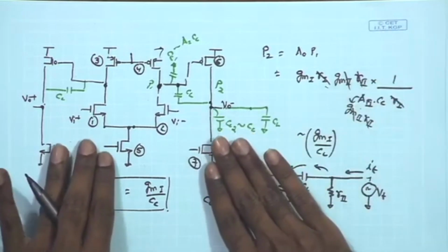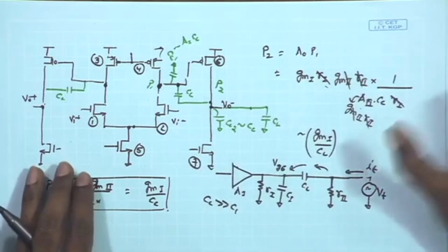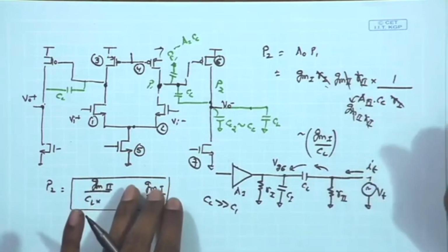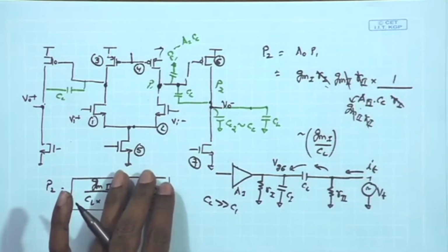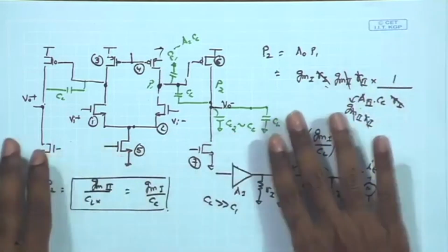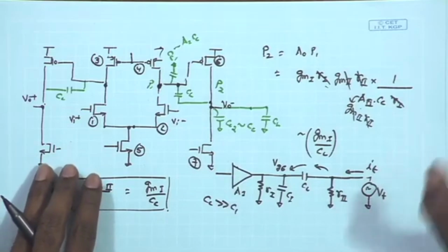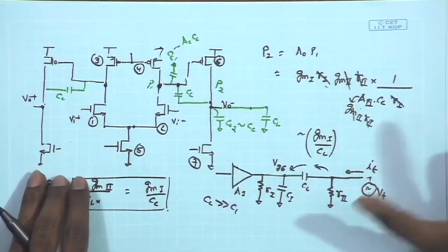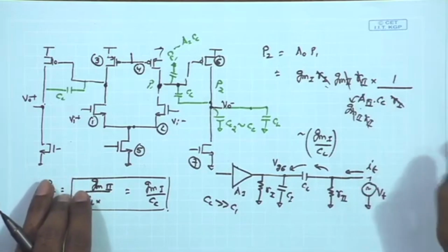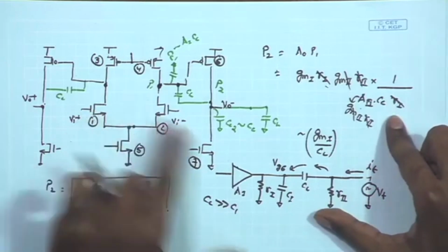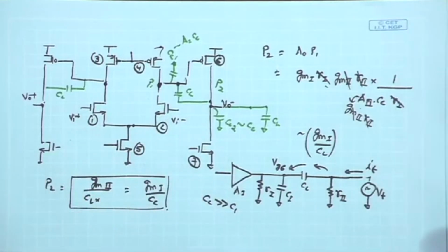If it is a single loop, then we will see that even for the error amplifier, the common mode feedback is not going to have a significant effect; the pole of that amplifier is also going to lie at very high frequencies. As we have discussed, if you are having a single loop, just to reduce the overall loop gain, we keep the gain of the error amplifier pretty small by having a direct connected load for both the drains. In that case, the dominant poles come only from the first two stages of the amplifier, and the error amplifier does not contribute significantly to the pole.